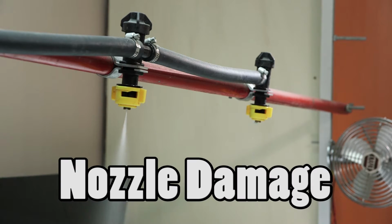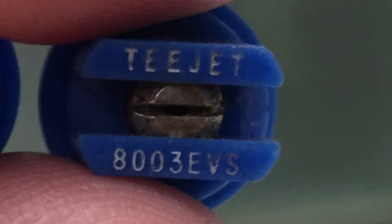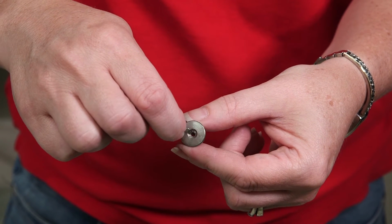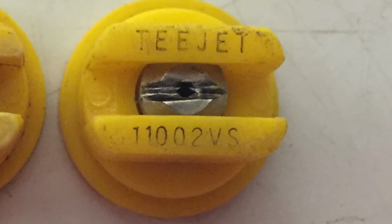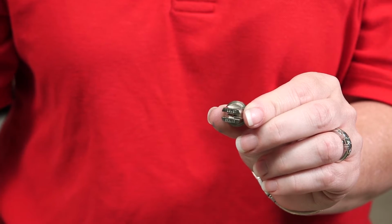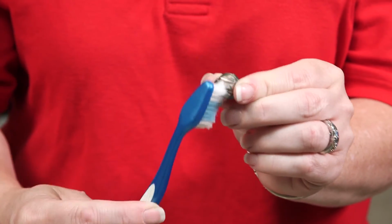The next demonstration will show the differences between a damaged nozzle and a new nozzle. Nozzle performance varies greatly between new and damaged nozzles. Damage can change the diameter of the opening, which affects your application rate. Sometimes people will attempt to unplug a nozzle with a wire or nail. Trying to clean a nozzle with a wire or nail will likely ruin it. If you need to clean a nozzle, consider using an old toothbrush or something else that is softer than plastic.